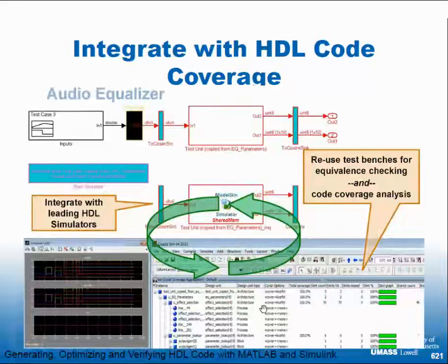So you can integrate this together. We haven't really seen this, but this is a coverage tool. This is the tree of the design. So the top level, internal levels below that, these are actual modules. And then these are the coverage of the model. Of course they show them all at 100%. But usually if you're in this dashboard and you tell the simulator to run coverage and you open up the design tree, you see these grow, get to high numbers, but a lot of times you see one that isn't getting tested effectively. It's not getting stimulated, so you don't see that.